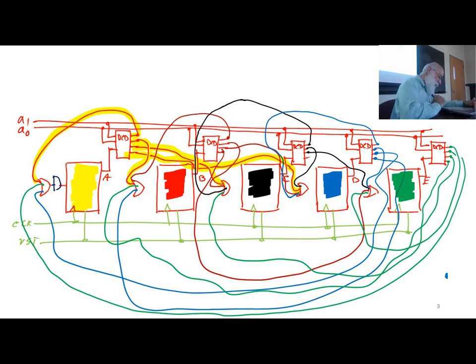I put an AND gate here. This becomes my init input. Let's call it init and not reset. And this becomes the inverter. So if init is 1, I am initializing this. I'm sorry, this is going to be 1, so I have to put an OR gate. By the way, you can reuse the existing OR gate. If init is 1, I'm pushing a 1 into this. And then if init is 1, I am killing this, this, and this.